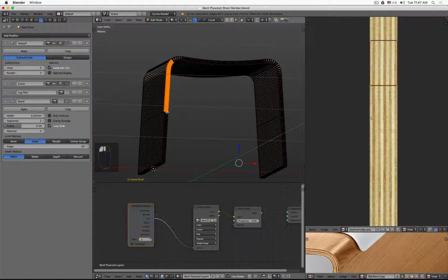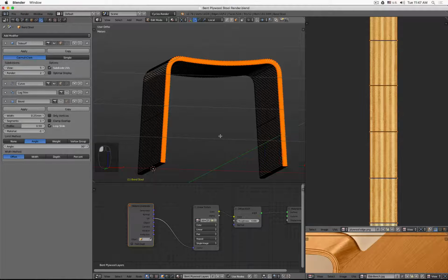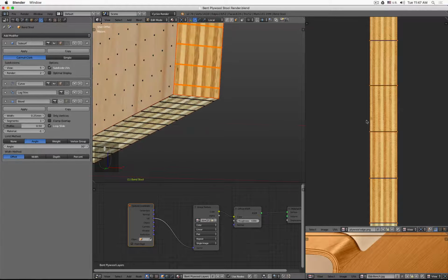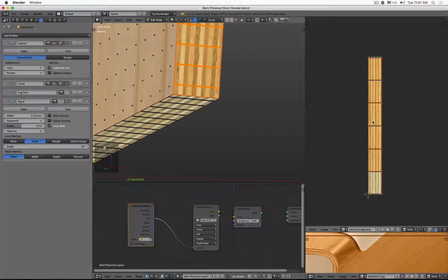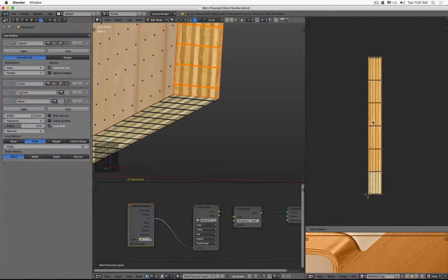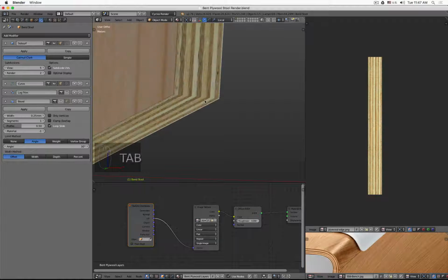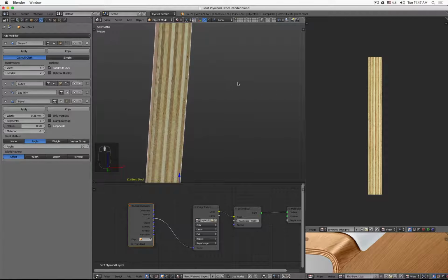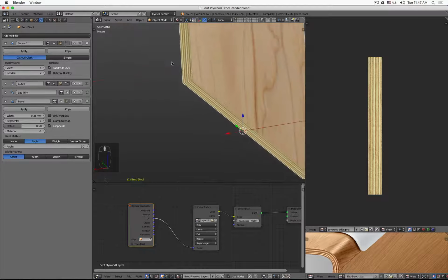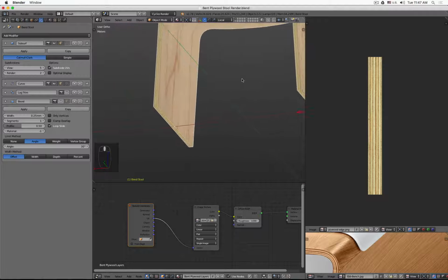Let's go back to edit mode. And now I would like to select this face, this face, this, and this. Okay. And I could rotate it, or I think Control M and then X will flip it. So I don't rotate it, I just mirror it. So now you see I switched the directions of the material, and now here also they all line up perfectly. Good.